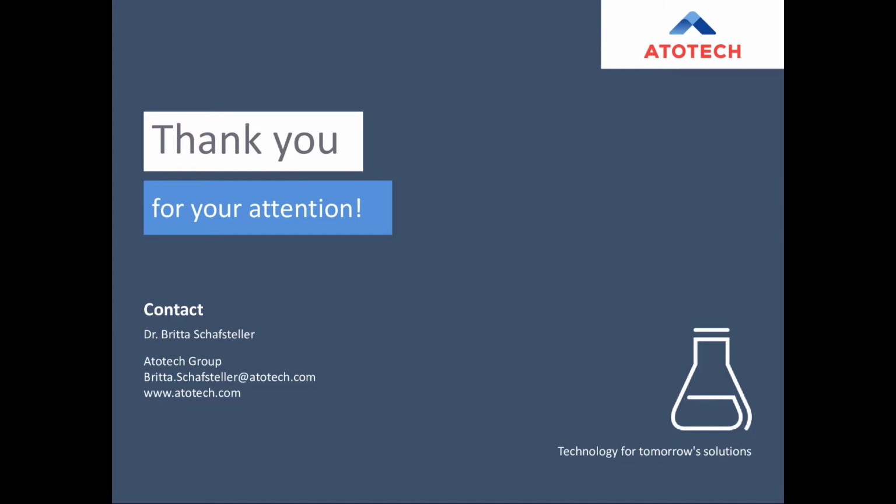If more than 60% of all the locations that we checked have a level 0 or 1, then this is a rating of 1. And if more than 40% of the locations show a level 3, then this is a rating of 3. And a rating of 2 would be then everything else, what is in between. And so this is how we judge and how we also do our development, and which also helps to determine tendencies in the gold bars development, to see which goes in the right or wrong direction. But now with the G-Bond 2, it's really just 0.